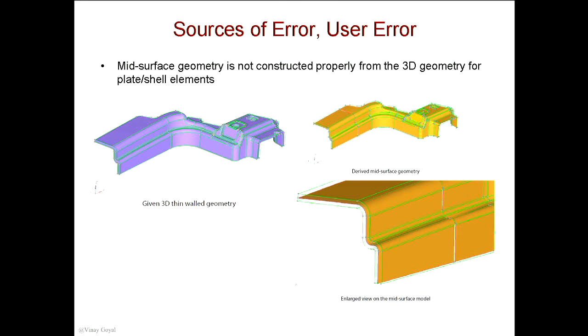So for example, if the thickness is varying, right, you want to keep track of that, because then the shell elements here, you'll have to specify thicker or thinner depending upon how the thickness varies, right? We know that the thickness is an important parameter for the shell elements. And so you want to make sure you're doing that correctly, applying those section properties accurately in the models, okay? Any questions? No?